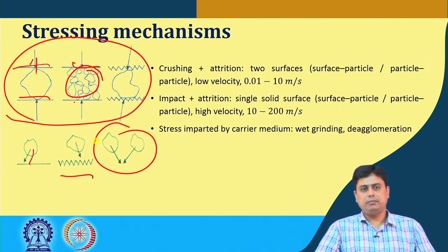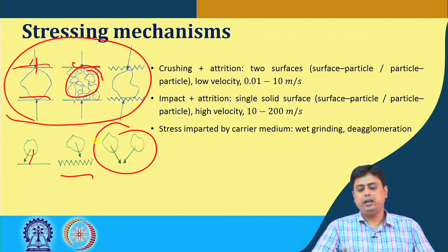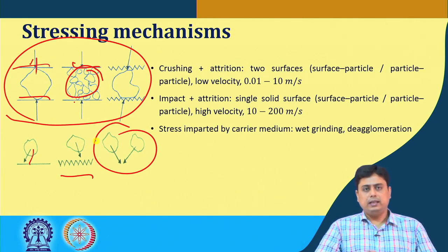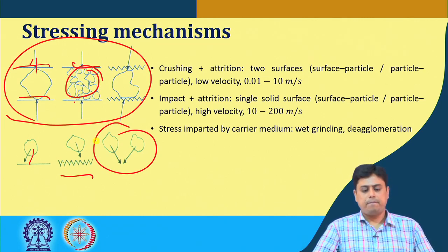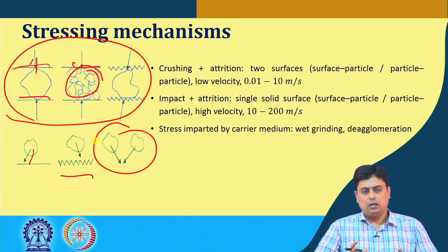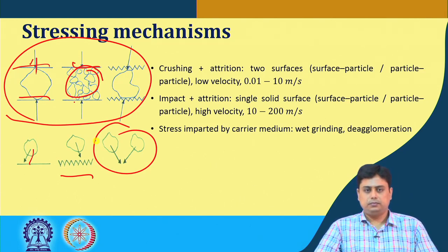The third mechanism can be the stress imparted by the carrier medium, that is wet grinding, deagglomeration, such kinds of phenomena. So, based on these mechanisms, the existing equipment can be classified, or in other words, this equipment works on one of these mechanisms or a combination of these mechanisms.